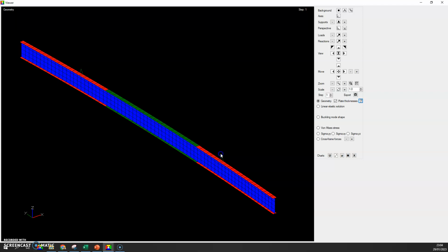You can see the lift points here, which kind of represent the clamps, on both sides. These are modeled with axial member with a high stiffness, and they are pinned at the top. And so 30 inches, you remember that number, this would represent the distance between this point here and the top of the flange.